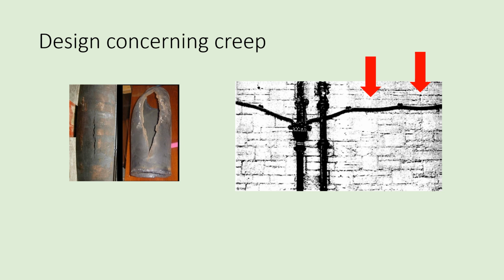These generalized equations that we just learned are useful when predicting when a component will fail due to creep deformation, which can be important during the design of materials and components. And as we stated in the beginning, it tends to be more important at higher temperatures and less important at lower temperatures. But as we can see in these two examples, and we'll go over, just because it's low temperature doesn't mean creep won't occur.